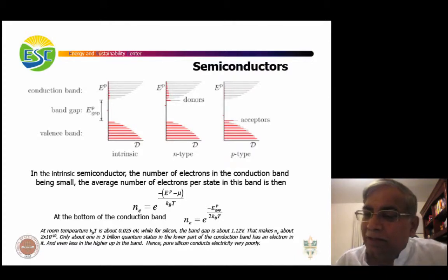These will move valence band electrons into the conduction band, thus creating electron hole pairs. In equilibrium, this creation of electron hole pairs must be balanced by the removal of an identical amount of electron hole pairs, and the removal of pairs occurs through recombination, in which conduction band electrons drop back into the valence band. So when these electrons jump into the conduction band, you have to take them out very quickly, otherwise they recombine and they regenerate.